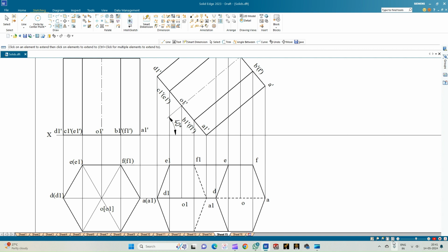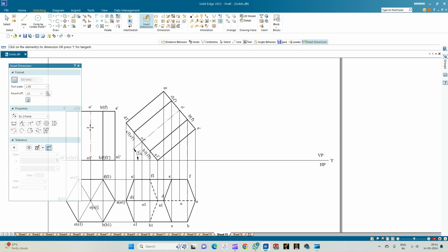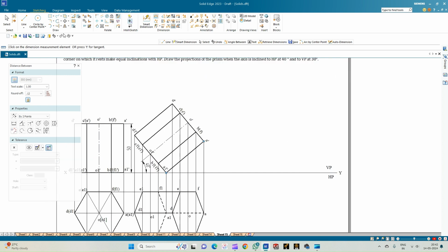So now we need to construct the beta angle. For that, the procedure is, let us first measure the axis length in its first position, which is equal to 50 mm, and then the axis length in its second position. So the distorted axis is going to measure around 38.3 mm. These two data are required for us to construct the beta angle.